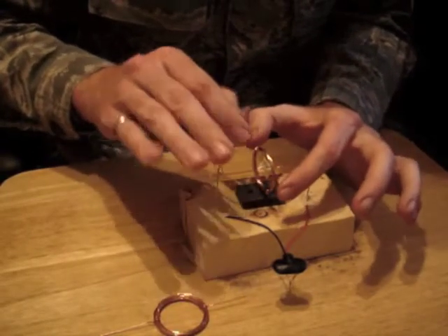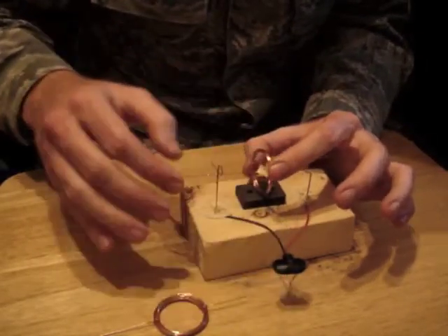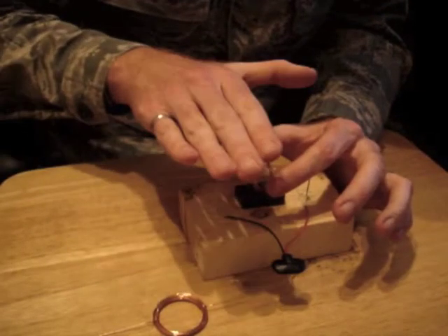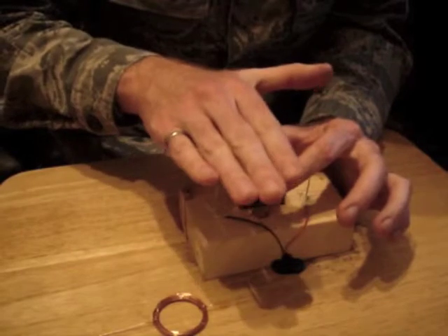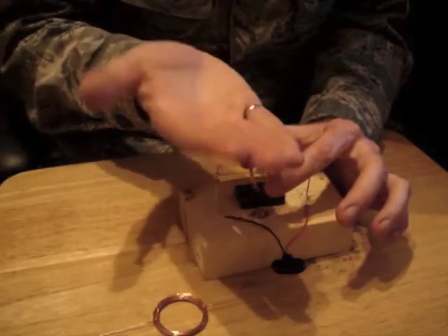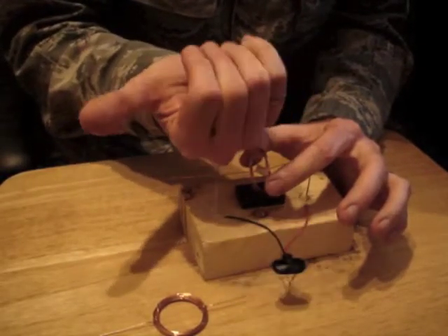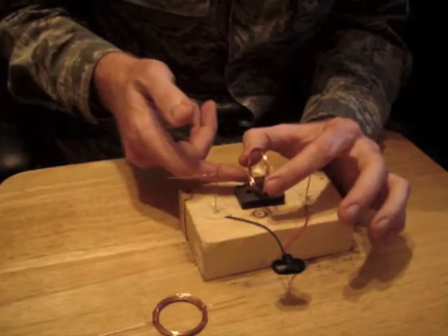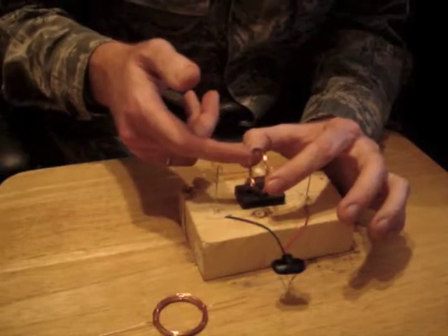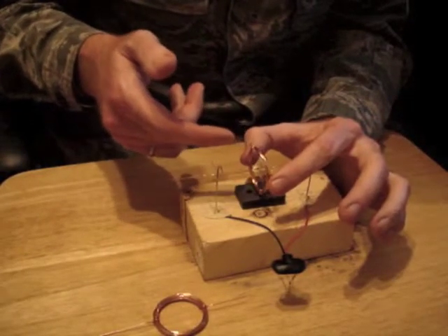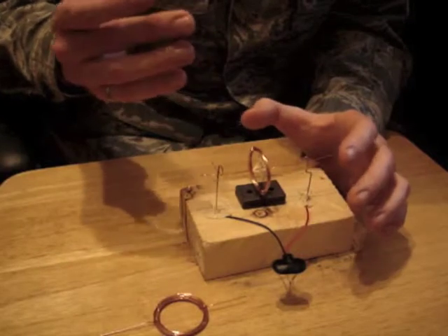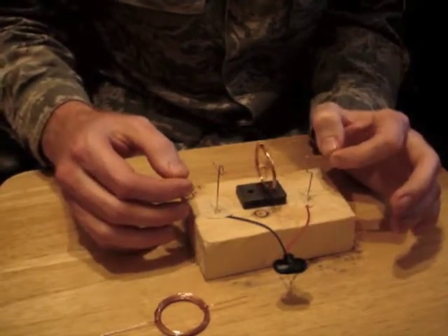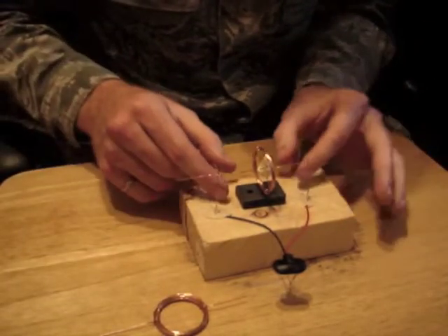When the current is connected, it will flow in this direction, and following the right-hand rule, curling the fingers in the direction of the magnetic field, the force will go that way. The same thing happens all around the rotor, but there will be no resultant rotational force because the configuration is incorrect.